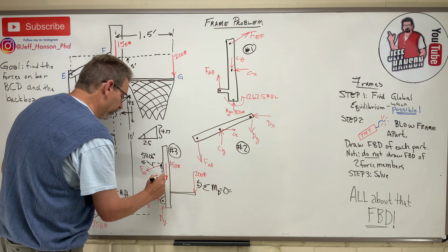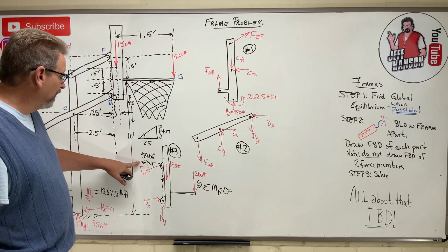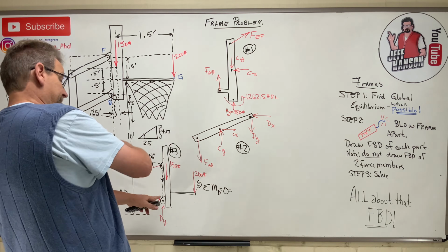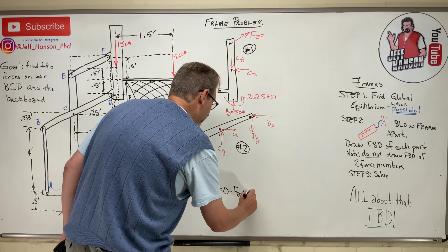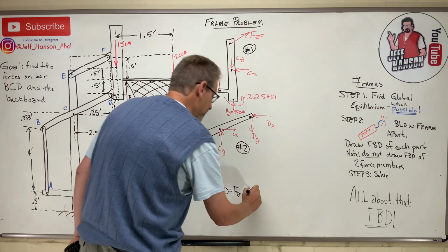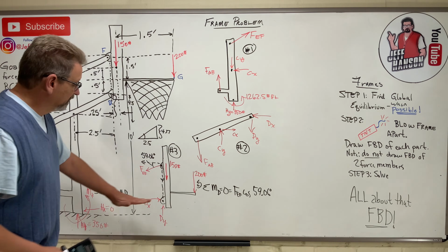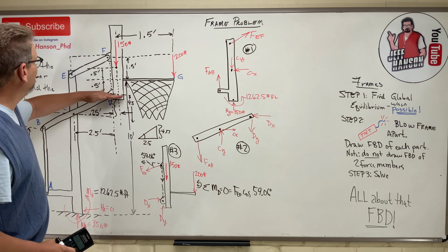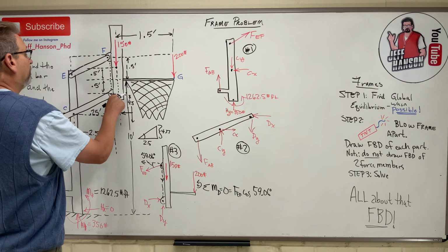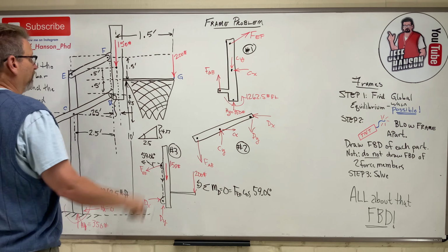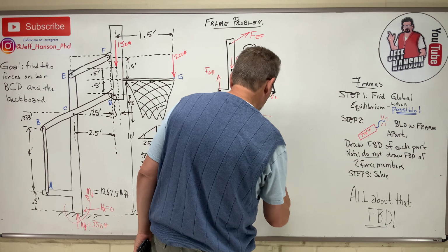Well, this one's a zero force. Look, it goes right through point D, doesn't it? So that's the only one I want, okay? And that one rotates me positive. So EF cosine of 59.06, times how far away? From D up to there is what? 0.5 plus 1.5. How about 2? Goodness gracious, there's a lot of dimensions on this problem.